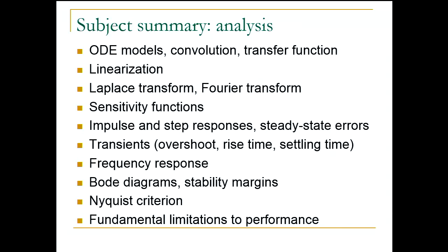So in a closed loop system, in a canonical form, you would have a reference input. You would have several disturbances. You would have input disturbance, output disturbance, measurement noise. Now, these sensitivity functions explain relationships between pairs of input, or given input, and output. Right? So we considered outputs either to be the output of the plant or the control output, or in other words, control signal. All of these sensitivities are capturing different aspects of the behavioral performance, or call it whatever you want. So features of the system. Features of the system are captured by these sensitivity functions.